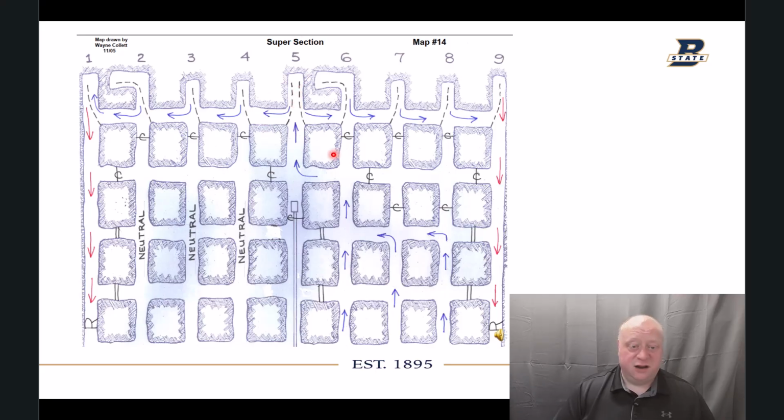to split the air. And I got to admit that I'm sure it's happened somewhere, but I've never seen this before in my life. Maybe it has. Maybe it hasn't. And then returns down both sides. They kept 4 neutrals. I think that's excessive. Especially given that you don't have one of the other neutrals on the other side of the belt. Now that might make sense, having neutrals on both sides. But that's my opinion. If this provides enough air for this section, then you go ahead and ventilate it like this. But anywho,